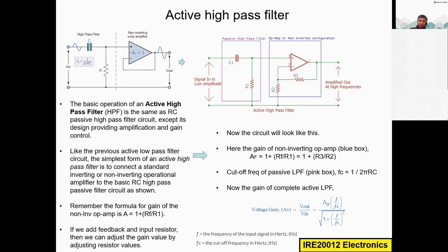So if I want to separate the two stages, I can include this voltage follower between two stages, but I want to also have some amplification. Then instead of having this typical buffer or voltage follower, I am going to add some resistor, and then I can control the gain, so I can amplify the signal at the output instead of having the same amplitude. So the same circuit, just modified here a little bit.